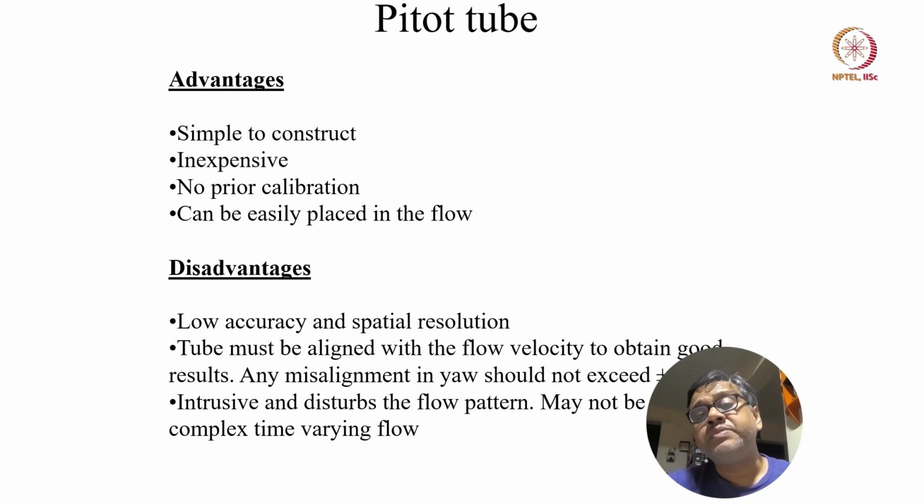So it may not be therefore valid for complex and time varying flow field, or the flow field which has got a lot of structures. For laminar well behaved flow field, this is an option to go ahead with a pitot tube. So that is the advantages and disadvantages of a pitot tube.